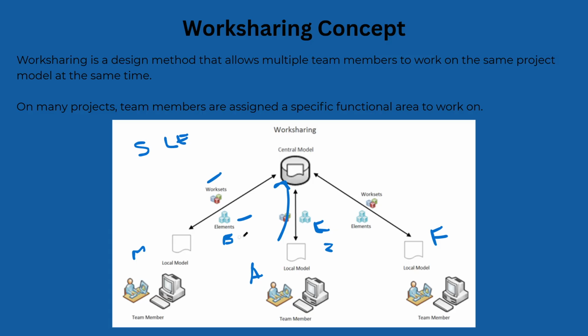That is why we use worksets or the element work sharing method, to have more control over our elements. Based on the scope of what exactly each person has to do on the project, they can work only on those elements. This can again be divided by building parts.